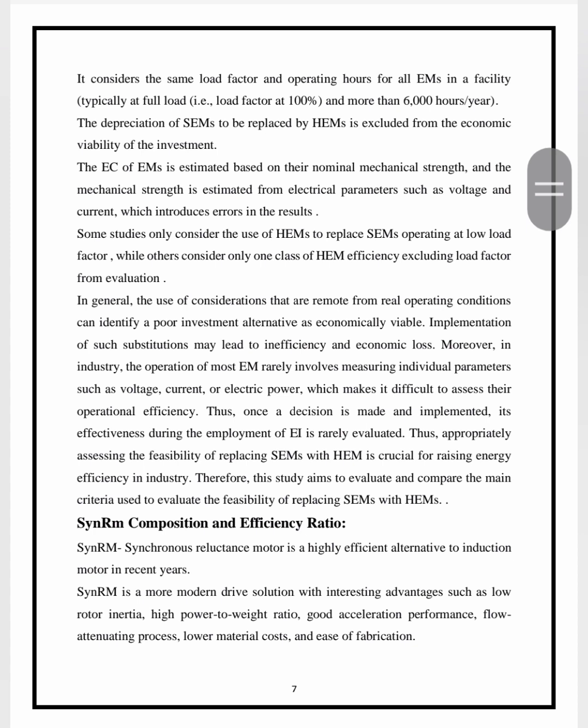The depreciation of standard efficiency motors to be replaced by high efficiency motors is excluded from the economic viability of the investment. The power of the electric motor is estimated based on its nominal mechanical power, and mechanical power is estimated from electrical parameters such as voltage and current, which introduces errors in the result.